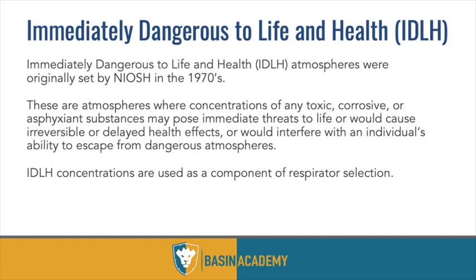And so at that level, that's where a respirator is required, like a full face piece respirator with supplied air, so that you're not breathing it in, right? That it's not impacting your lungs, etc. And that's for any toxin. In H2S, that's 100 parts, and SO2, it's 100 parts. But again, what we're seeing is that SO2 is known industry-wide to affect you at half the levels of H2S, but the record books, the OSHA rules, kind of put it in the same category, but keep that in mind.